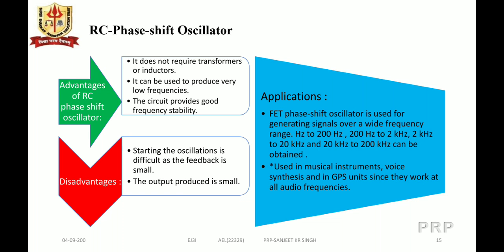Now what are the advantages of the RC phase shift oscillator? It does not require transformers or inductors. That is the major advantage. Secondly, it can be used to produce very low frequencies. And thirdly, the circuit provides good frequency stability.